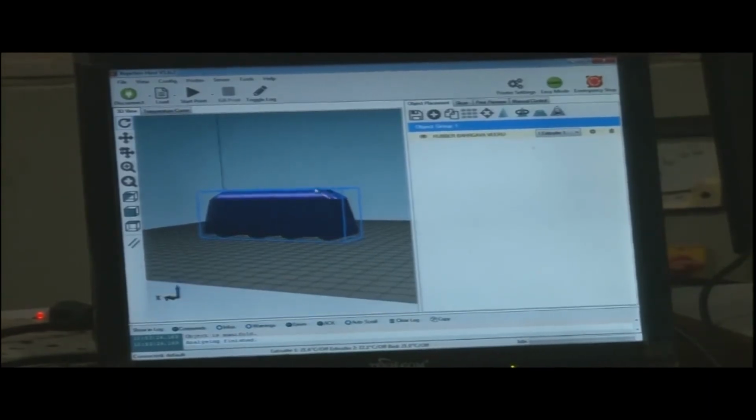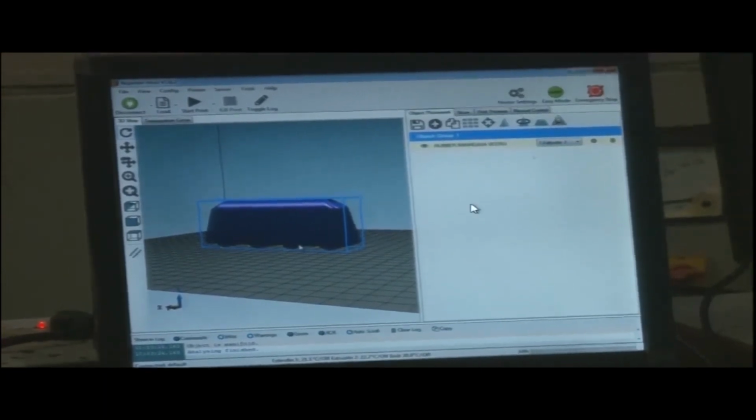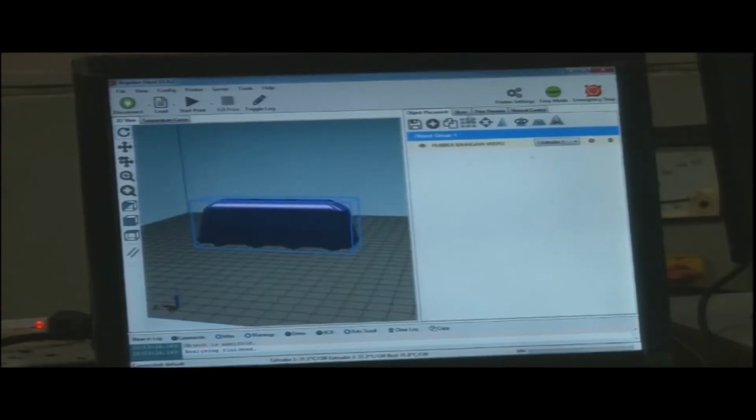The entire height of this job will be cut into a number of slices. How many layers there would be, the machine would decide. So we have to program in terms of slicing, and the machine will deposit one slice in one stroke, and this will be deposited layer by layer and finally becomes a complete job.